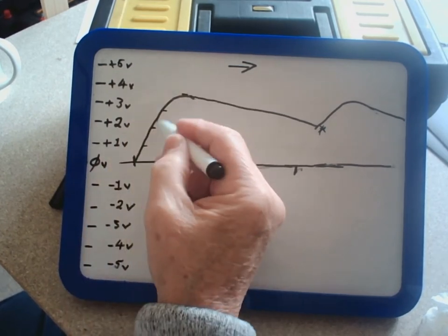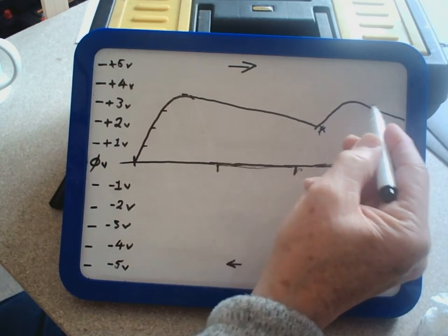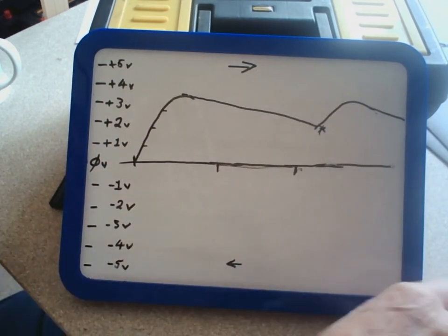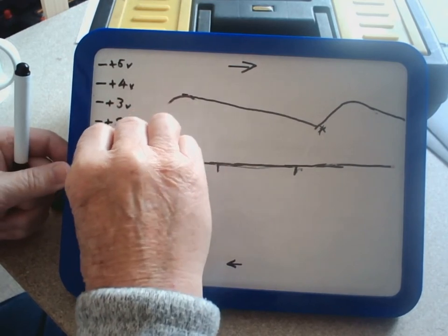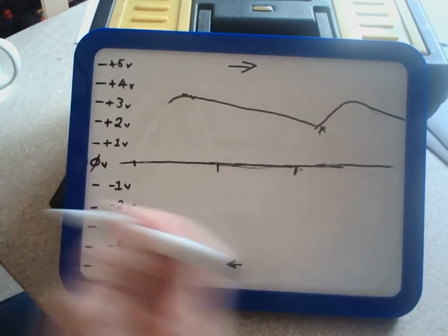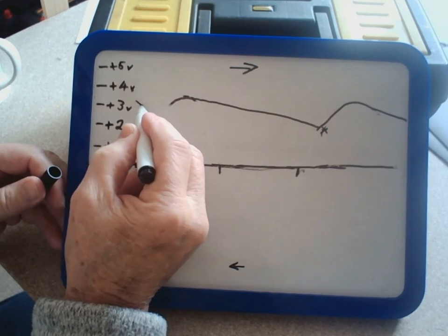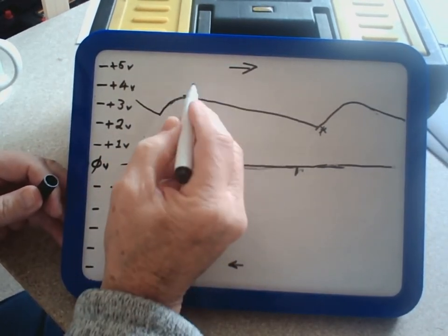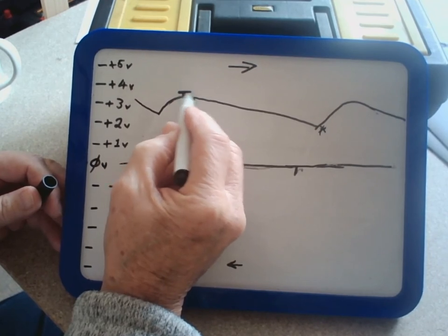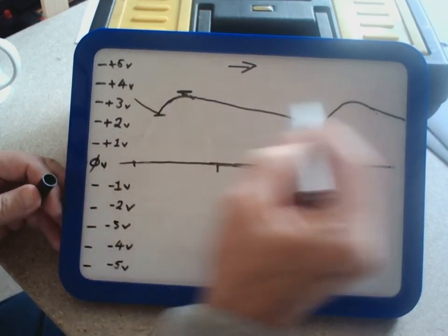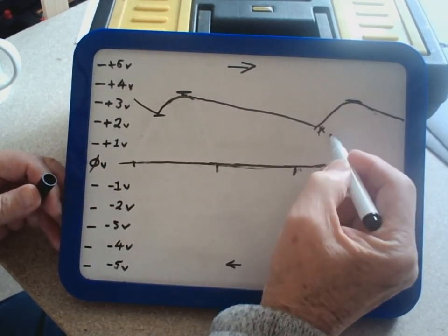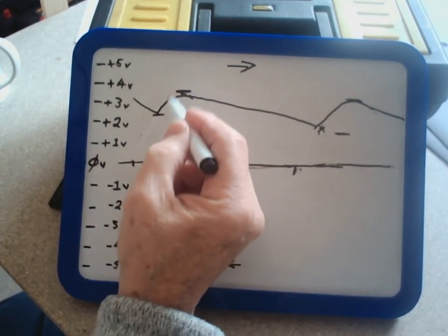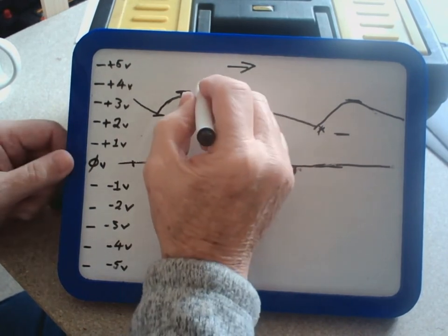But you may notice we still have a varying voltage on the supply line. If the capacitor was in circuit back here, the voltage would have been coming down, and so we still have a variation in voltage between this peak and that trough, and this peak and that trough, and this is called the ripple voltage.